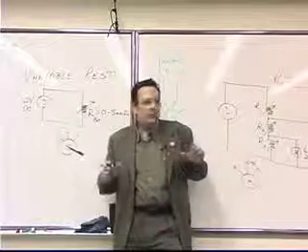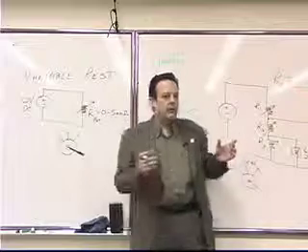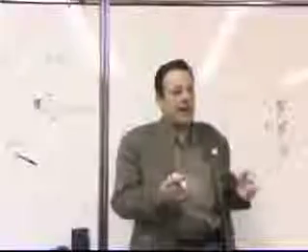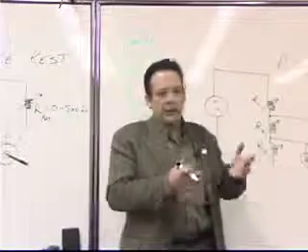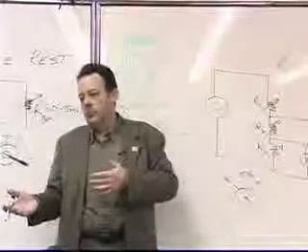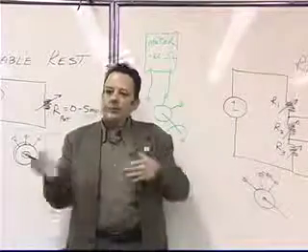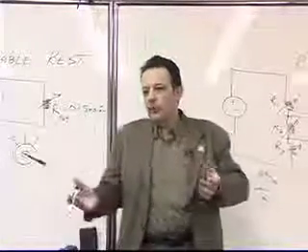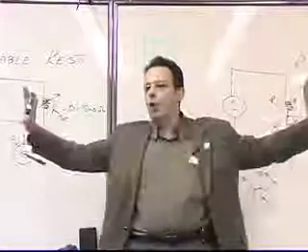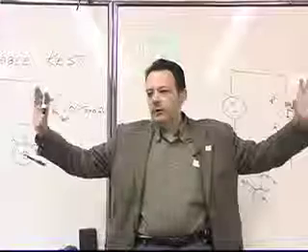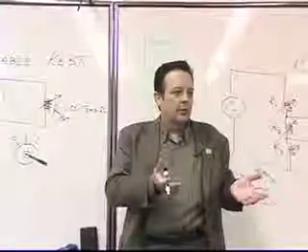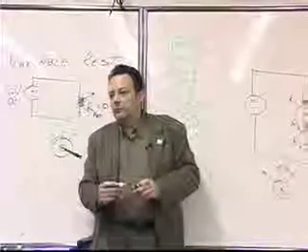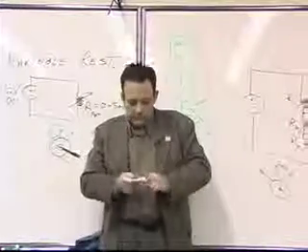Okay? And the person who has to go out in the field and hook something up that they can vary so that they can figure out what value should be inserted or substituted in order to make the equipment work. The latter is dangerous. The former allows you to come out to the field with everything that you need, de-energize the whole circuit, and then put in whatever you need, energize the circuit, and be very confident that it's going to work exactly the way that you designed it. Okay? Questions?